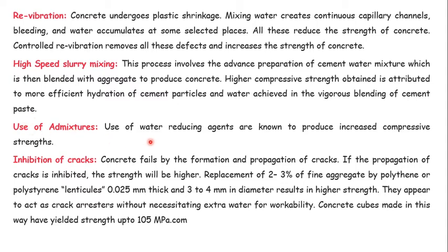Use of admixtures. Use of water reducing agents is also known to produce increased compressive strength, which we have already seen in the admixtures. Inhibition of cracks: concrete fails by the formation and propagation of cracks. If the propagation of cracks is inhibited, the strength will be higher. Replacement of 2 to 3% of fine aggregate by polythene or polystyrene lenticels 0.025 mm thick and 3 to 4 mm in diameter results in higher strength.